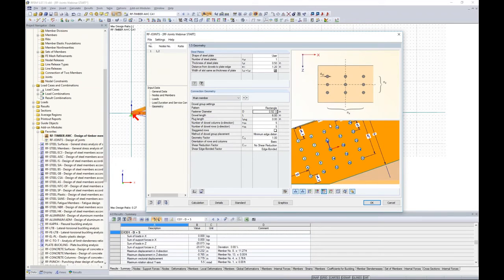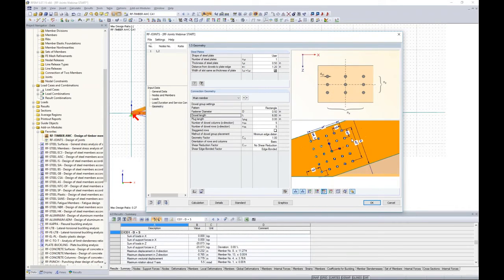We will set our fastener diameter to 0.5 inches. Now the dowel length is automatically calculated simply based on the thickness of my member, my glulam member. So this is set at 6 inches for the thickness of the member. Now perhaps I would like to not see the dowel holes, for example, and I want to put a plug on either side of these. Well, here's where you can set that plug length of maybe 0.5 inches. And you'll notice that the dowel length automatically takes that into consideration and reduces to 5 inches. For today, we will leave the plug length as 0.